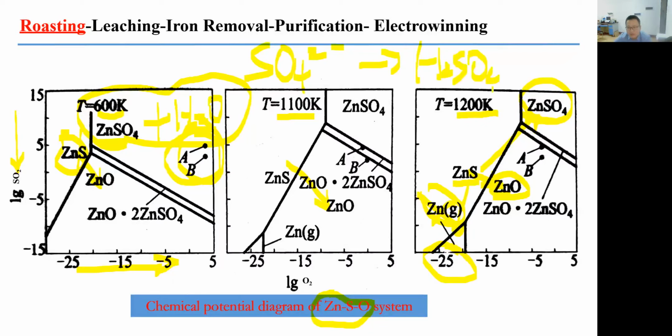As I have mentioned, in the electrowinning process, zinc deposits in the cathode, and in the anode, oxygen will form, and H plus will form in the anode as well. So these two will form the sulfuric acid. So this one cannot aggregate in the system, and this should be well monitored or should be balanced in this system.